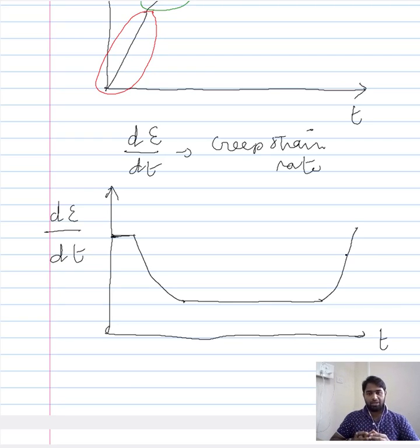So similar to the creep curve, wherein you had 3 or 4 stages depending on which approach you follow, we can also section this overall curve into different stages, meaning there can be stage 1, 2, 3 and 4, or, because this varies with the material, we can combine these two and treat this as stage 1. So this combines the instantaneous and transient creep region, so that is stage 1.